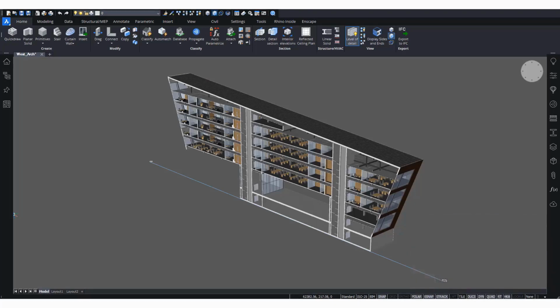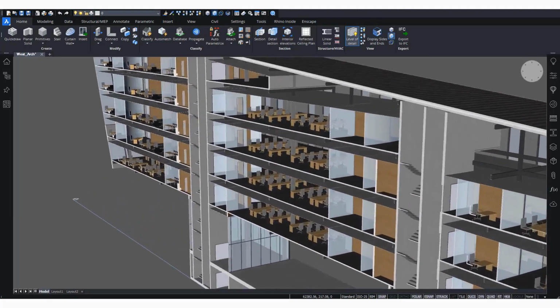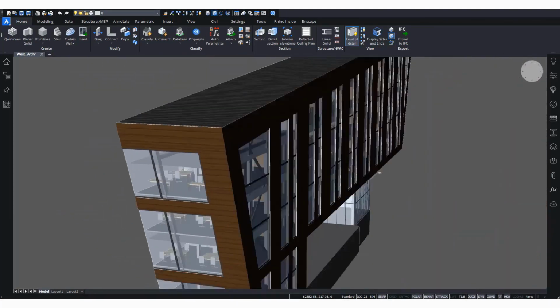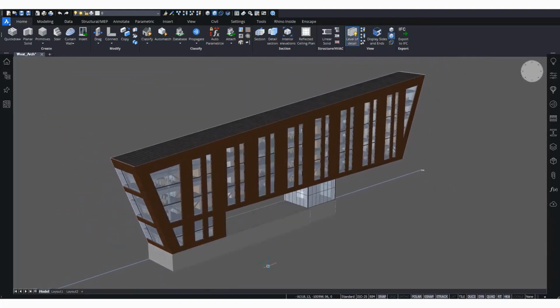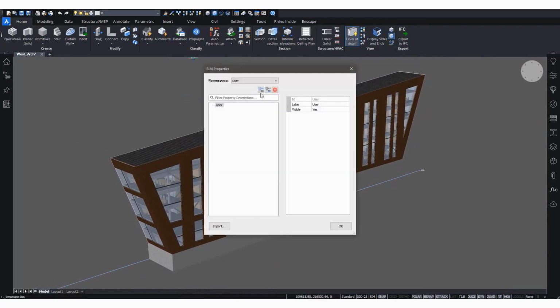First of all, I'll just focus again a bit on IFC. We have this example here of the West building that we covered in an earlier exercise already as well. And the first thing I want to show you is the custom property. So obviously, if you make custom properties, you can assign them to objects, and then when you export to IFC, of course, these custom properties will also be exported with it. So in this case, we're adding a custom property for Windows. Actually, one set with two properties inside it. One of them is cost, and the other one is manufacturer.